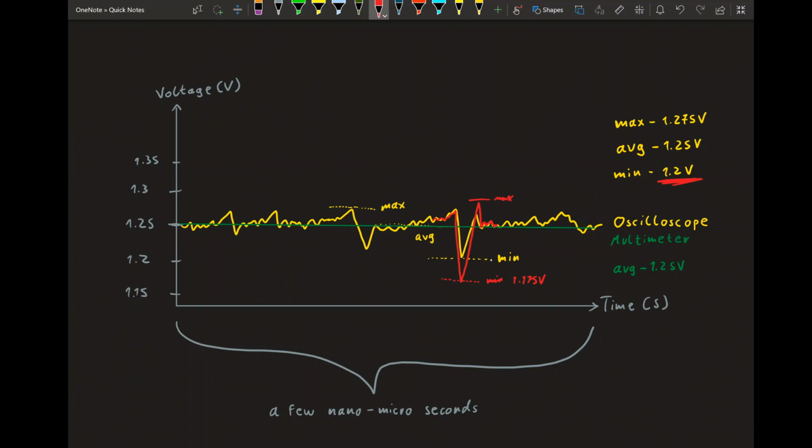That's why on a cheaper motherboard, you will need to set your average voltage higher to get the same clock as on a higher end motherboard, because the lower end motherboard has a sharper drop for its minimums. That's also why cap mods work, because cap mods do the opposite. They increase the minimum because your voltage drop is less, because you have some energy stored in your capacitors, so when the voltage drops, the capacitors release that energy and counteract the voltage drop so that it doesn't drop as low.